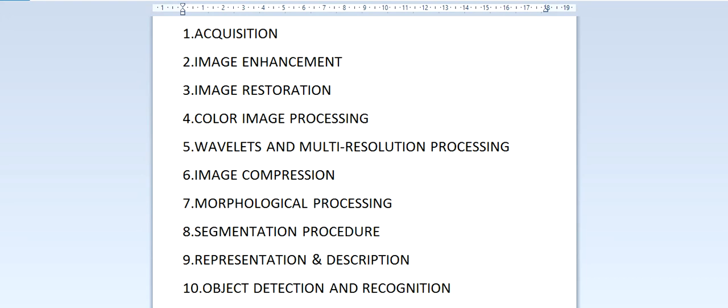Mostly this image acquisition depends on the hardware. We use cameras for getting the digitalized image. A camera consists of sensors inside them which measure the light intensity. There are sensors which convert the light into electrons, and there are also ADCs, that is analog to digital converters, inside the camera, which help us to convert the analog parameters into digital parameters. The sensors used may be CCD, which refers to charge coupled devices. It may also have CMOS inside them.